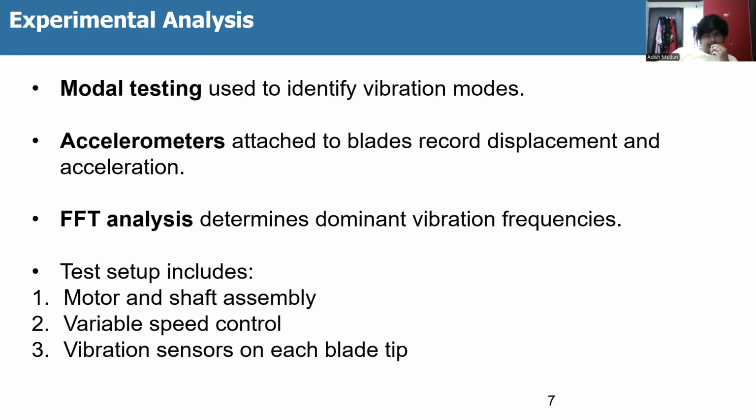So these are the main test setup components, along with FFT analysis and accelerometers. Modal testing is used to identify vibration modes.